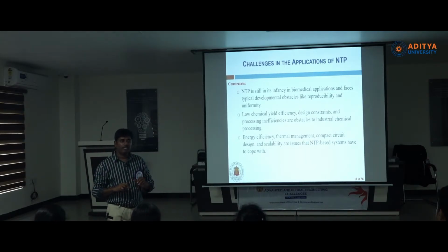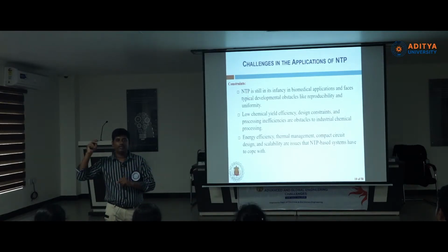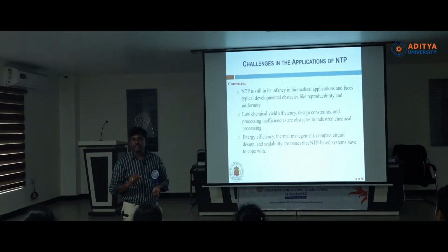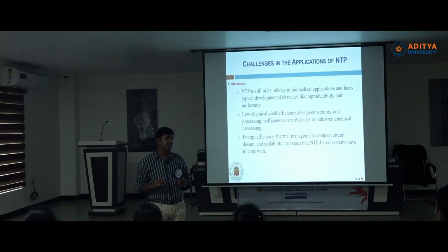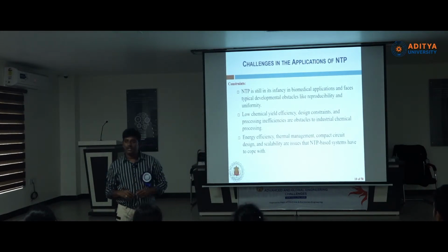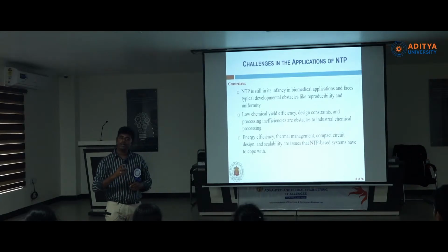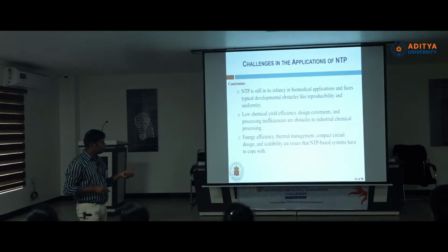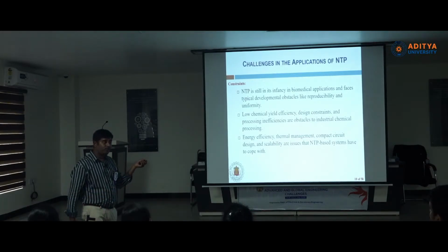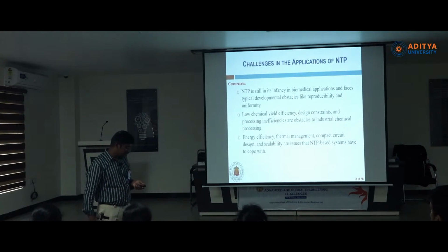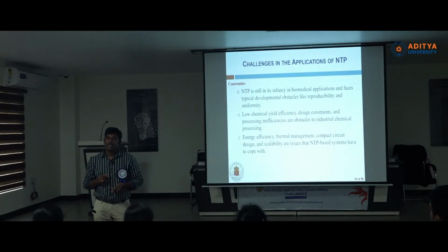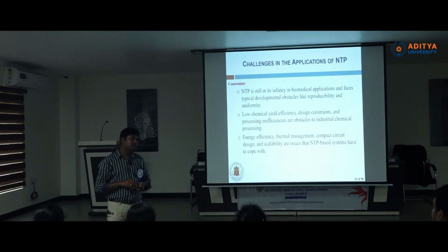How can you generate high voltage in that application? If you want to release a water treatment product, then it is a constraint, isn't it? High voltage generation equipment is larger than what small scale applications or small products need, so it is difficult for you to generate. Such research works you can do. In my PhD, when I was using this technique for diesel exhaust pollution control, we generated high voltage from a 12 volt battery. From a 12 volt battery, we generated 20 kV high voltage.